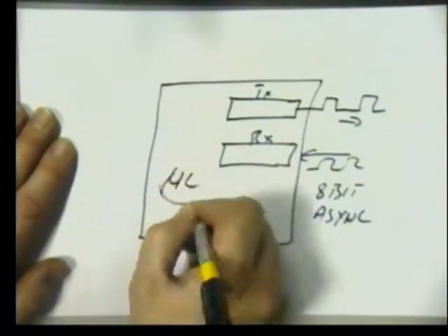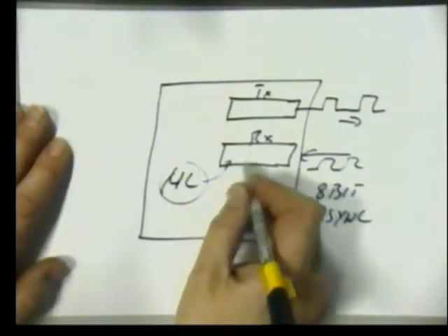Now, we can't afford to have our microcomputer continually monitoring the slow asynchronous link to say, has data arrived? The way it normally works is we have an interrupt, so that whenever a character is received, an interrupt is issued to say, "Oi, stop what you're doing, a character's arrived. Go and process the serial link," which could be a keyboard or a remote PC or a remote computer. But some slow data has now arrived, and it's all there, all 8 bits have arrived, and it says, oi, stop! I am the receiver interrupt, process me now, get the character.